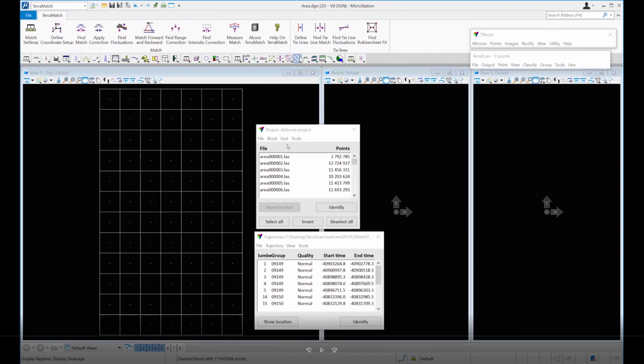This means that the ground surface can be compared between the flight lines and between overlapping flight lines. So you will have 2 ground surfaces in the overlap. And this means that you can compare these 2 lines or these 2 surfaces and get statistical output and observations of how well the flight lines fit.